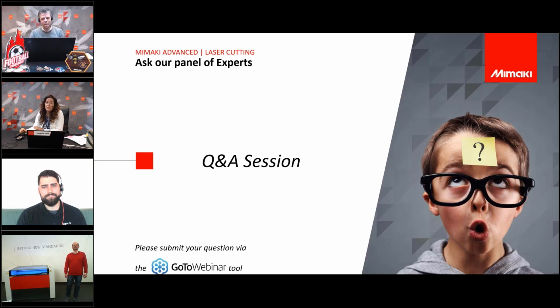Michael, as a product specialist, you can probably give an answer on that. Yeah, the best way is just to print first, get the edge marks at the right position, and then cut out. You will achieve accuracies around 0.2, 0.1 millimeters when it comes to overlap between the print and the cut contour, which is really hard if you work the other way around. So it's just the best process. First printing, get the edge marks right, and then laser cut along the print.